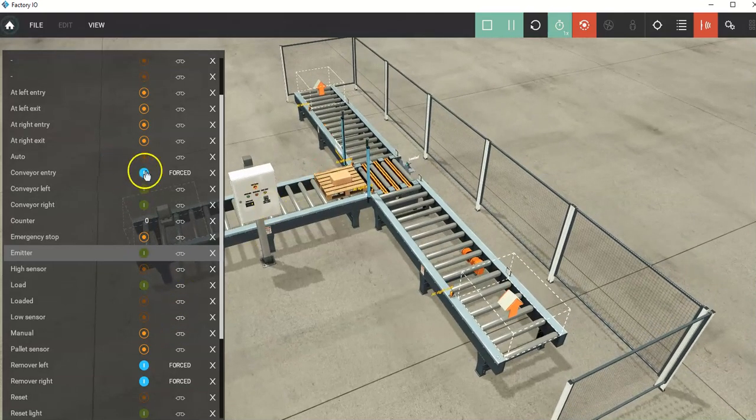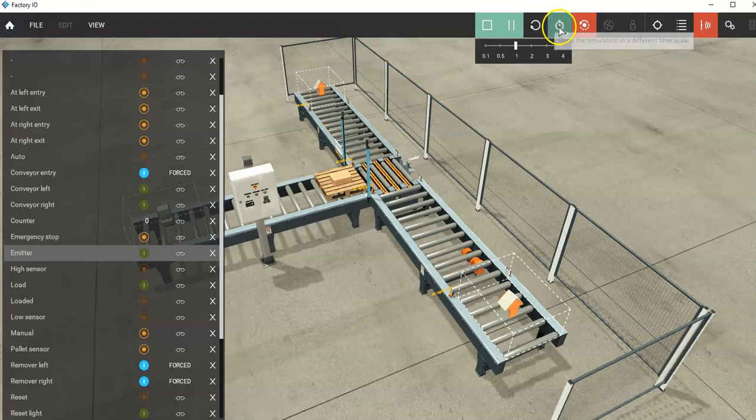So now what I'm going to do is start this up again, and we want to see what happens. I think I'll stop it again when the sensors for the box, the high sensor and the low sensor, go high. Now you either have a high box or a low box, so no matter what, the low sensor is going to go high. Actually, what I'll do is slow it down to half speed, then unpause it, and when that low sensor goes high, I'm going to try to repause it as quickly as I can.